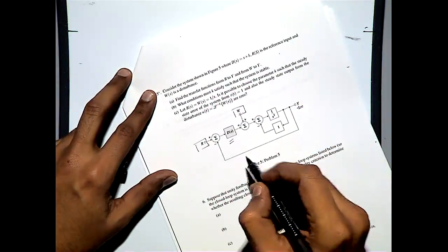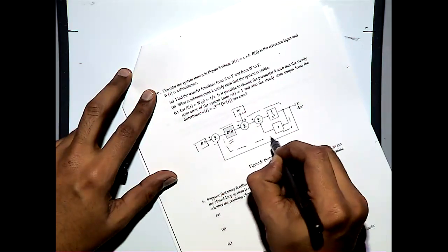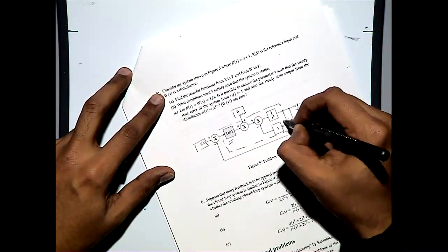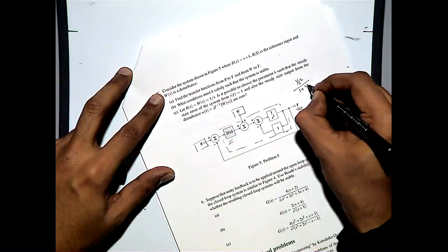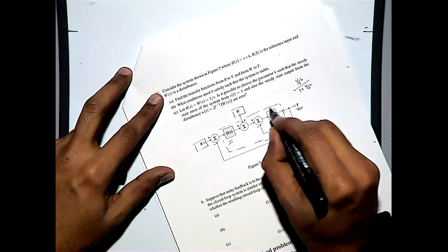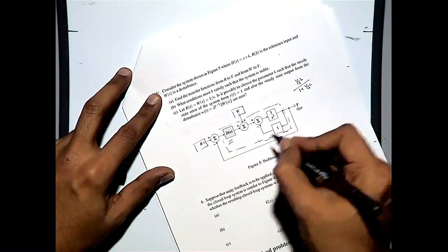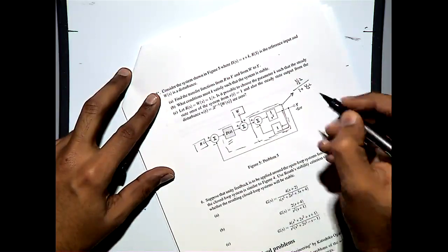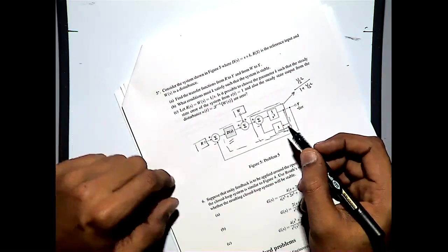For that one, first we need to find out the equivalent transfer function of this internal block. By using the transfer function algebra, we can do that one. Why? Because this one will be 1 by s square divided by 1 plus 1 by s square, which will be the transfer function of this internal feedback loop, and the total transfer function of this one. So which means this is exactly this expression.